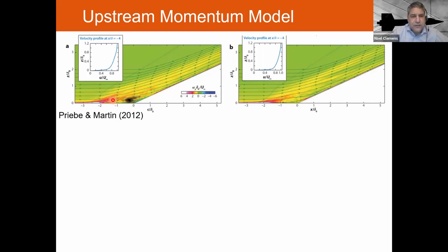And so the fact that the streamlines are deflected upwards means that there had to be, from Newton's second law, a pressure force that acted in order to deflect it. So the pressure here in this corner will be higher than the pressure in this corner once that bubble is gone. And then they also gave us the velocity profiles upstream of this interaction at the time these images were selected. So then you can actually get the magnitude of the velocity fluctuation, and also what the pressure changes.